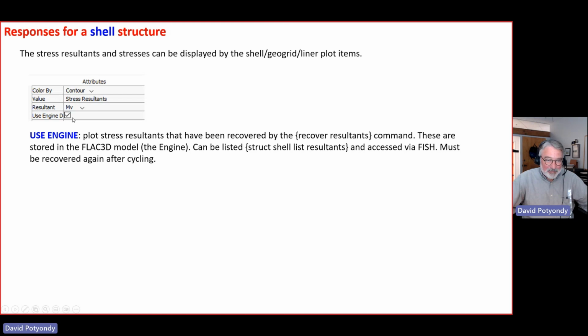Okay. When you give the recovery command, structural shell recover resultants, it then stores that inside of the FLAC3D model. And then you can access that with fish. You can list it with a structural shell list command. Okay. That's the data. It's using the engine stored in the computational engine.